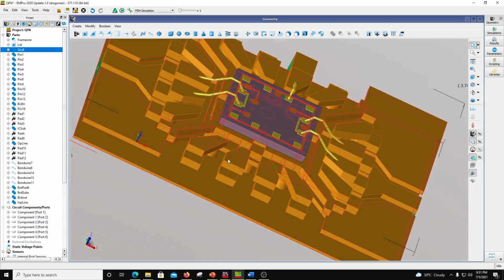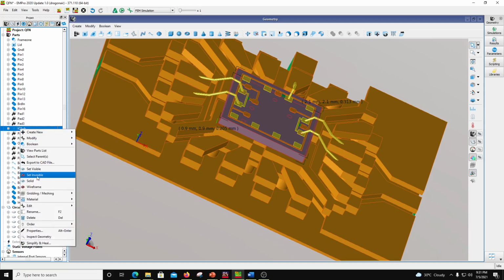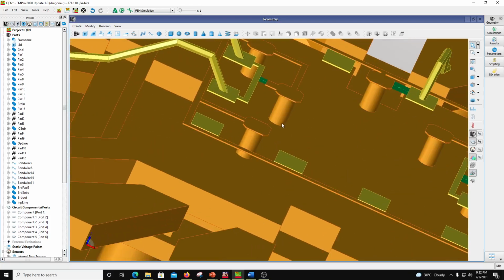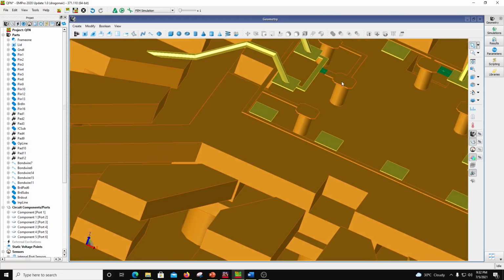And if this is gallium arsenide or nitride, ground is over there, and then it comes up to the chip through a via. So let me just turn on this one. What you see is going to be gallium arsenide or gallium nitride, or maybe silicon or silicon germanium, or it can be silicon carbide, right? So let me switch off this also. Okay, so now what you see is these vias, which are substrate vias. Now these substrate vias come up, right, and bring the ground onto the chip, right? So everything is going to be relative to this ground. Okay, and the ground is not 0 volts.